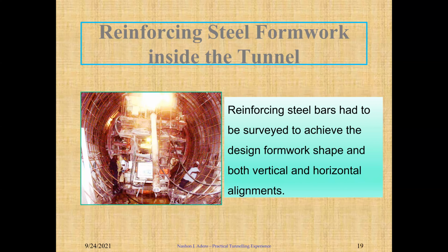I said it is a headrace tunnel, which is circular in shape. So even that formwork for construction must be circular. It must be set out to be well aligned horizontally as a horizontal cylinder with the correct diameter and correct slope. And based on that, those steel formworks are mounted on it.